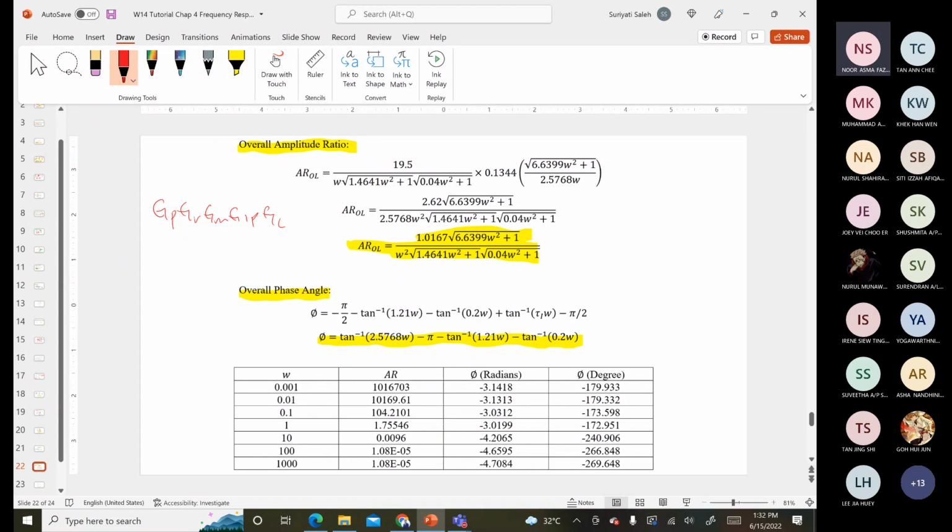When we obtain all of them, we will perform the Bode diagram, the gain margin and the phase margin, to evaluate whether the process is stable or not. Before this, with no controller, we didn't know the value of the controller parameters. Now that we have them, we can evaluate the stability.